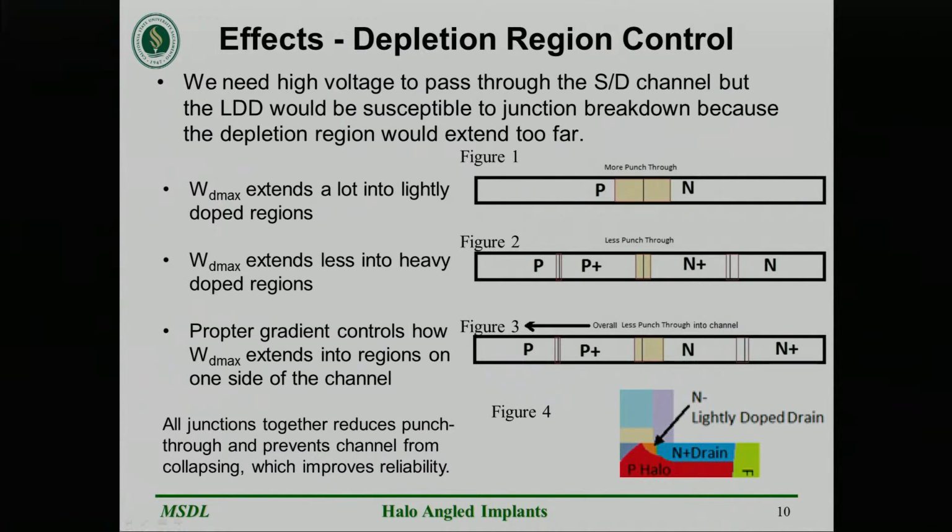the short channel length. This also prevents the depletion region width from extending too far into the channel, limiting punch-through and allowing the depletion region to extend in the needed direction, away from the channel, for improving things like DIBL. Further away, the N+ limits the depletion region extension for more reduced VT roll-off, but with a non-inverted doping again. The next slide will show more details.